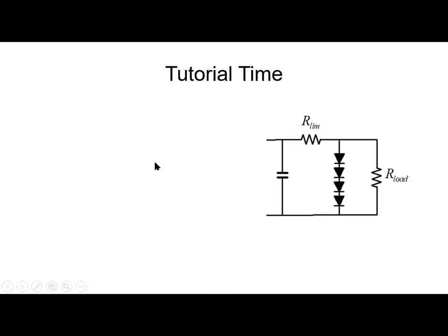I am not drawing the full wave rectifier on the left of the capacitor, but we all know it is there. We are told the voltage in the capacitor is changing between a peak value of 7 volts and with a ripple of 2 volts. That is, the voltage here at the capacitor varies between 5 and 7 volts.